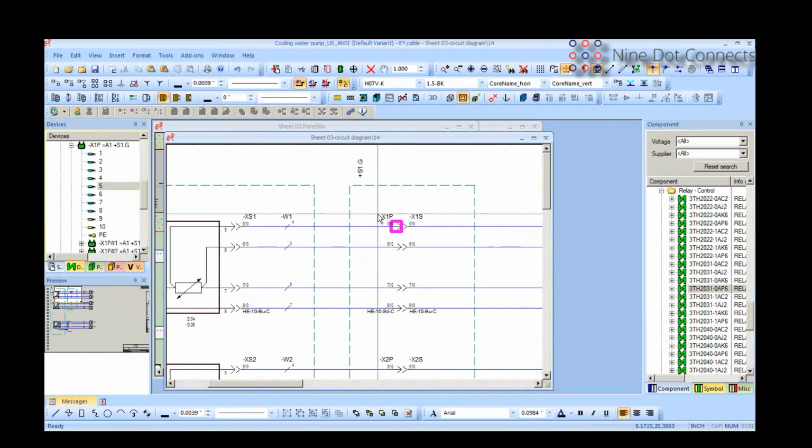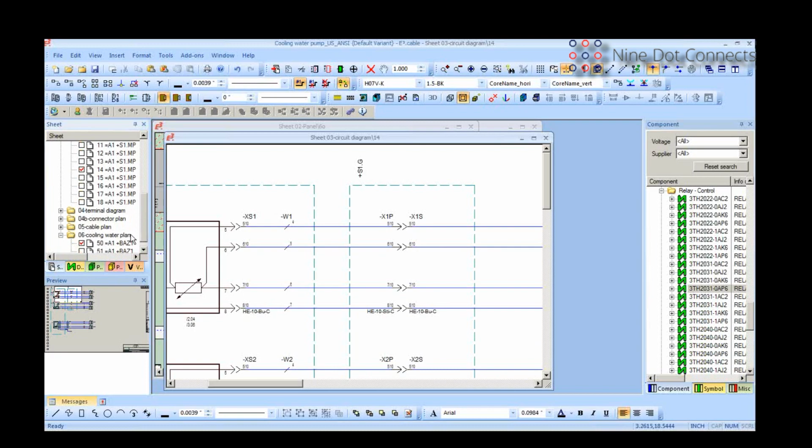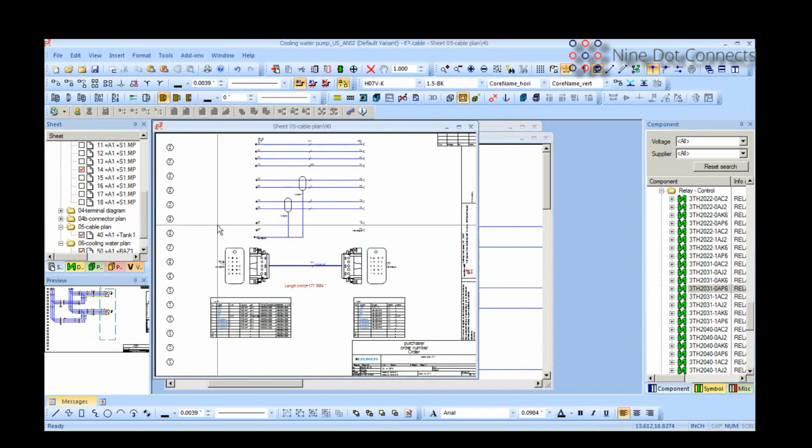So within a project, I can have my cable, my conductors of my cables and wires spread throughout the schematic itself, which makes it a little bit difficult to actually track them. But because of the functionality provided with cable, I can go in and say, well, what I want to do is have another drawing, and in this case, I'll use this cable pan drawing, that shows all of the cables, or the conductors of this cable in this case.